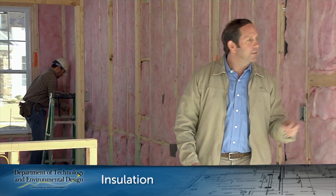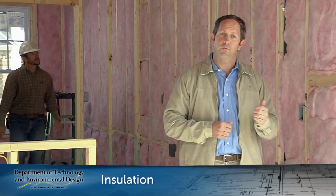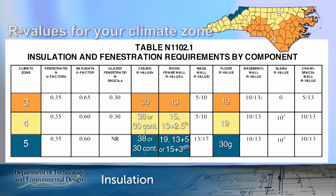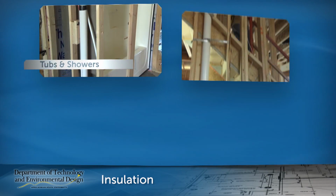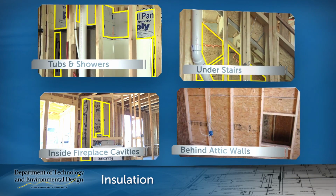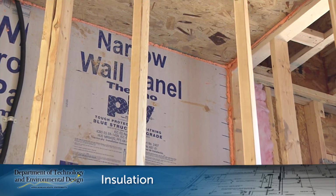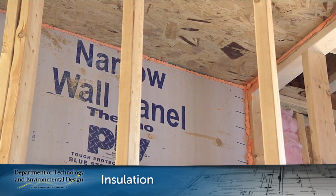Insulation should be installed in constant contact with the air barrier and should be substantially free of gaps, voids, or compression. Insulation must also be properly installed and encapsulated behind tubs and showers, under stairs, inside fireplace cavities, and behind attic walls. For framed walls, cavity insulation must be surrounded on all sides with a rigid material or an air barrier such as plywood, sheetrock, or thermal ply.